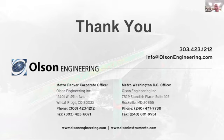Okay, and I think, as I understand it, we are seeing some groups actually interested to do impact echo scanning as quality assurance, particularly in early stages, for building new post-tension bridges. It's commonly done that way in China. We've sold a lot of our systems to China. They're building so many post-tension bridges. I've personally been in China and demonstrated. So they are doing that check in particular.